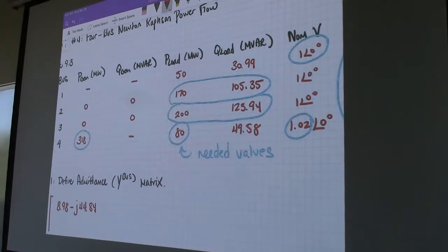And we're not going to get into anything about matrix inversion. Sometimes power systems courses will, like when I took this as a graduate student, the most difficult part of this problem is inverting the matrix when you talk about it from the computer end, and that's what takes up the most time. So a lot of courses will go into faster ways to invert matrices, LU decomposition and all that type of stuff, but we're not going to have a chance. So we're just going to be going MATLAB or calculator to the -1 and let it handle it.